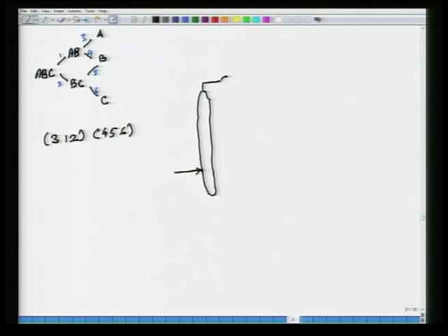Section 3 has got a condenser associated with it. Taken out pure A out here. As I go up from the feed, there will come a location where there is essentially no C. That's where I take out a side draw, and I don't know whether that side draw would be vapor or liquid. We'll figure that out in a little bit. I think it will be liquid. Yeah. Okay. So I'm taking out AB.